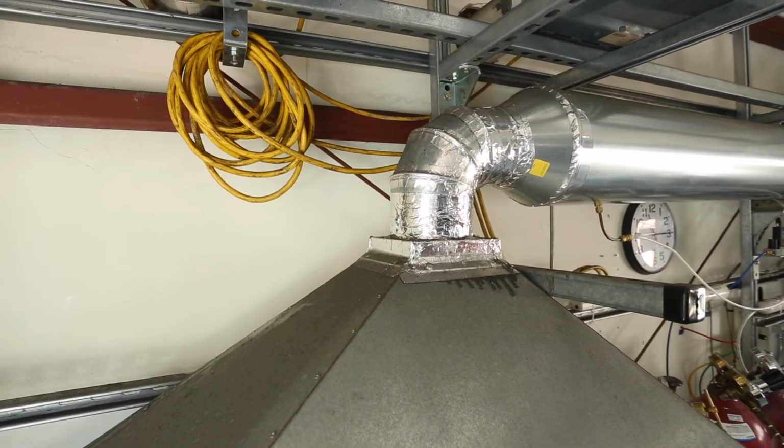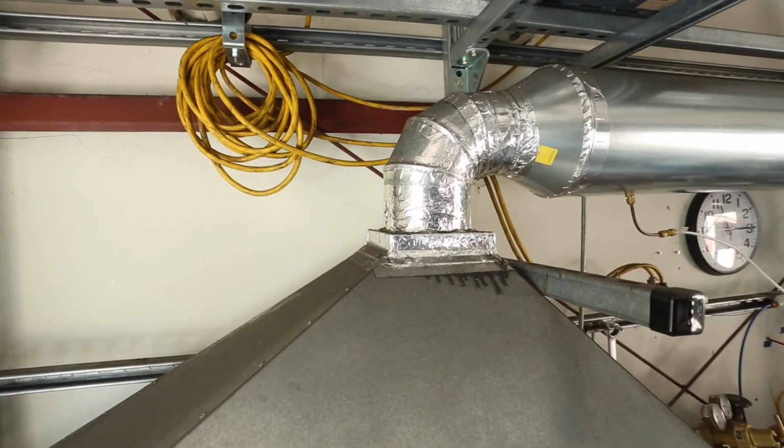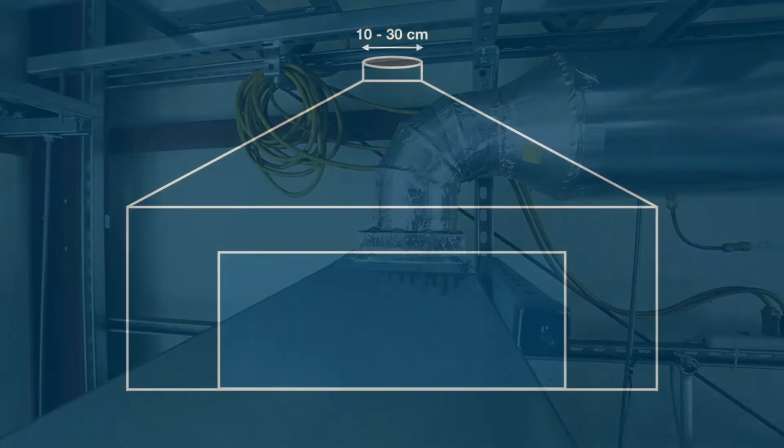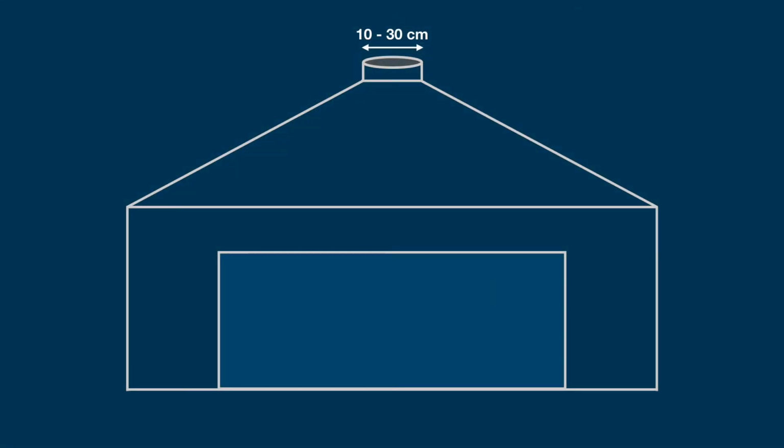Finally, you need to transition your rectangular cross-section hood into a circular cross-section duct. This can be difficult to fabricate by hand, but there are commercially available products designed specifically to transition from square to round cross-section ducting. By reducing sharp corners, you can reduce eddies and particle loss. The transition terminates at a circular duct, which the ISO recommends be between 10 and 30 centimeters in diameter.